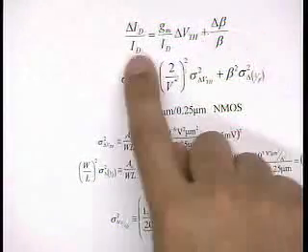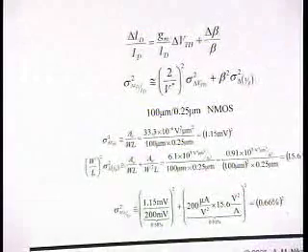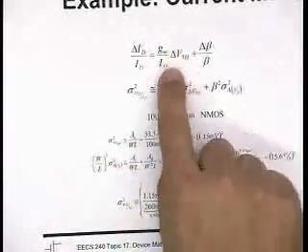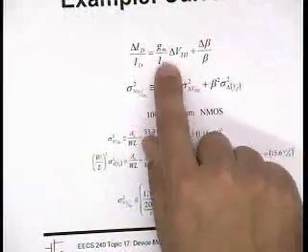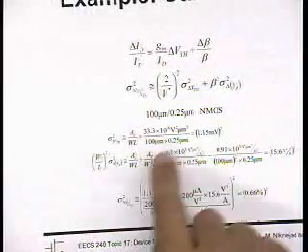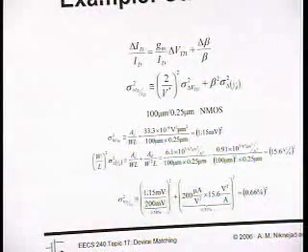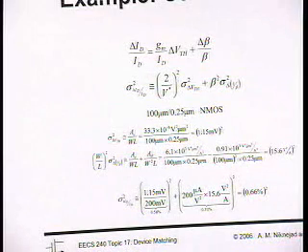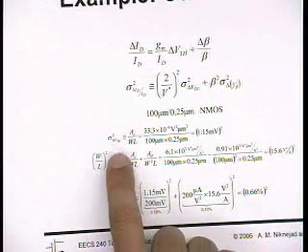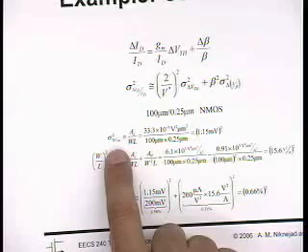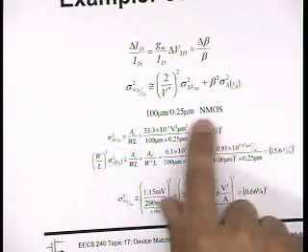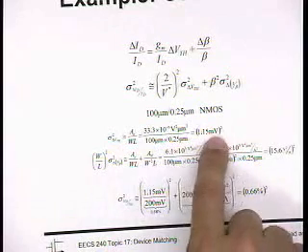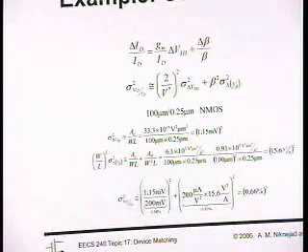This is an equation for current mismatch for a current mirror, and given a certain value of VGS effective, right, GM over ID, you can control the mismatch. So for this particular example, to calculate the standard deviation of the VT mismatch, we plug in the area of our transistor. We use this coefficient here, and we find the standard deviation is 1 millivolt for this large device.